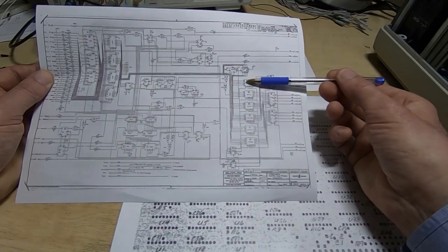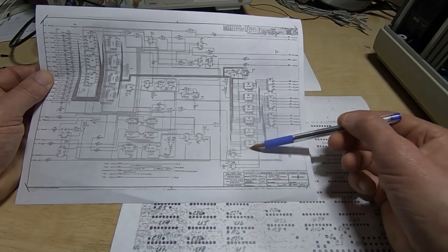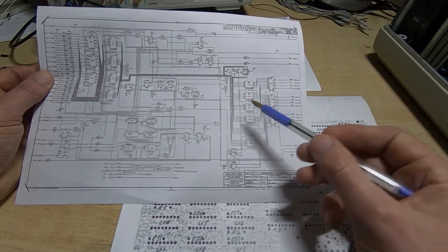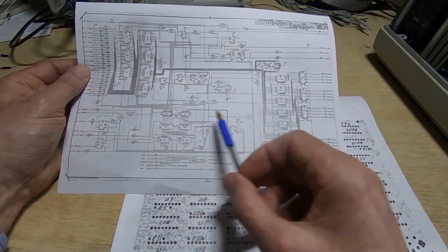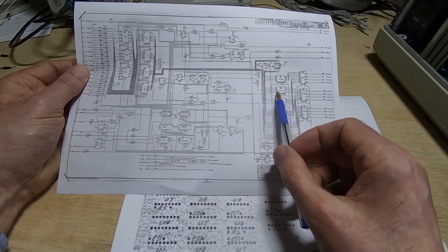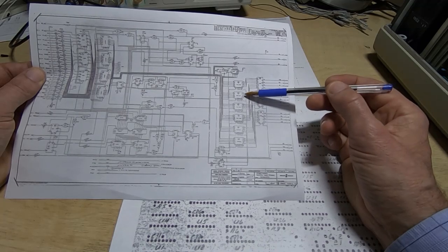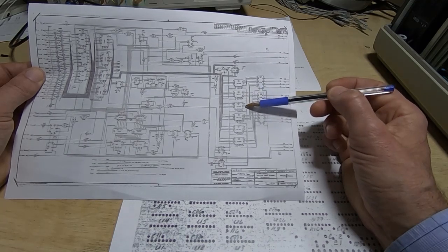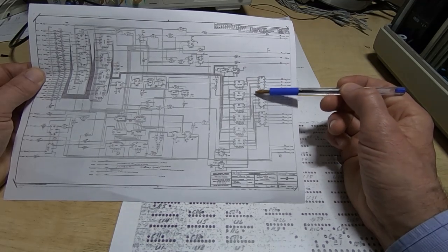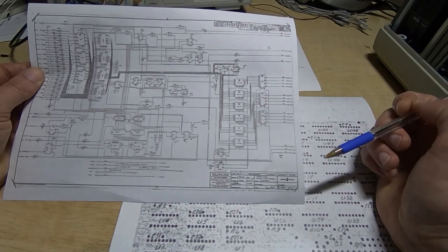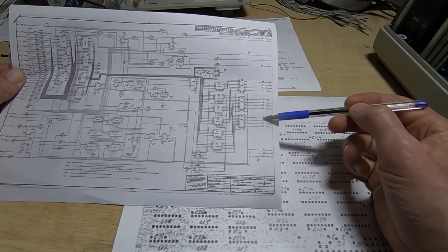So this effectively contains a buffer for a line of characters and then another buffer for another line of characters. So the data comes into this. These are circulated through, so this runs through at high speed. It's constantly feeding data through here. Comes out, and you notice there are 12 bits. So we have 8 bits for the current character we want to display, and then another 4 bits are for the particular characteristics that we want to apply to that character. So we get these 12 bits.